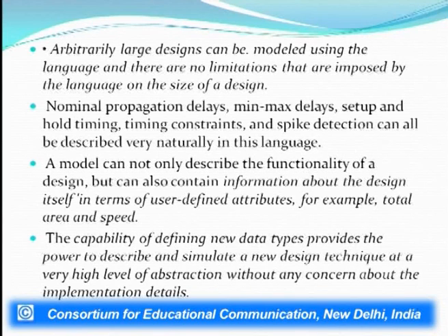However, for an efficient design, it is always better to break down the large design into different modules, and the modules can later be designed using HDL. However, for large designs, the support from VHDL is available. Now, nominal propagation delays, the minimum and maximum, often called the min-max delays, the setup and hold timings, the timing constraints, and the spike detection. All of these attributes can be described very naturally in this language.